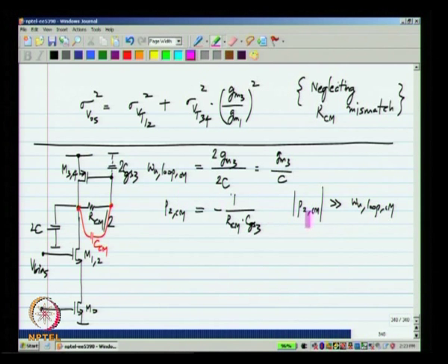That is, if the pole happens to be at a low enough frequency, then you will have ringing, you will have poor phase margin in the common mode feedback loop. The way to fix it is to have this capacitor which adds a 0 or a negative delay. So, in that case you can again calculate the poles and zeros. Okay.